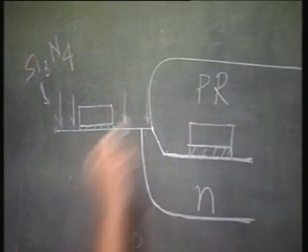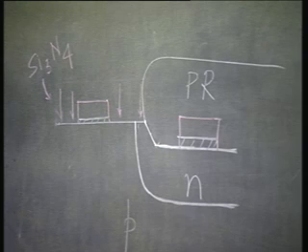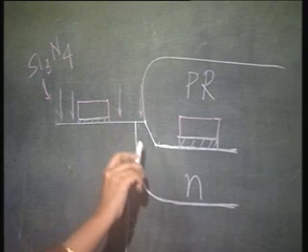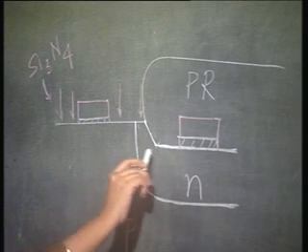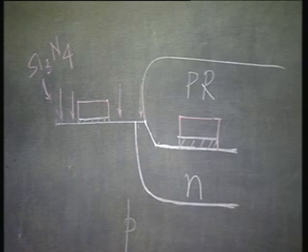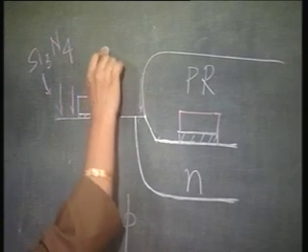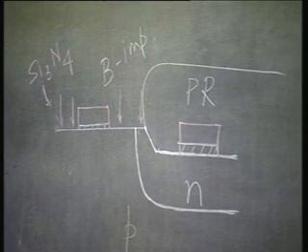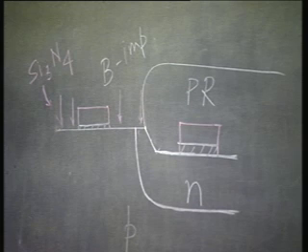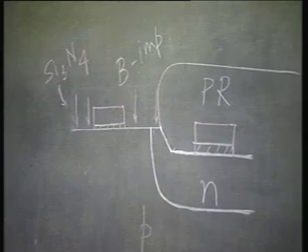You are using ion implantation, so no problem, photoresist can be used as a mask, and there also you see this indentation will come in very useful to align the photoresist mask onto the Nwell. Okay. So, now you have done the boron implantation, which is the channel stop implantation for the NMOS, and in the next step you grow the thick oxide.